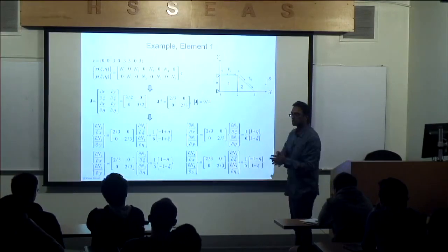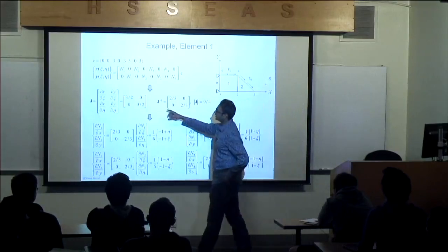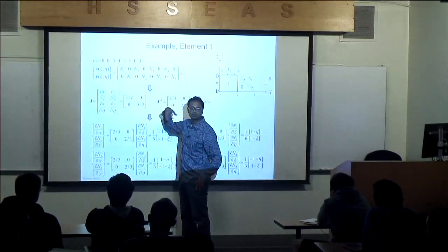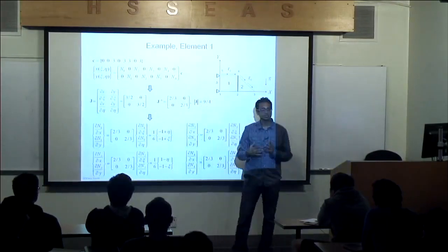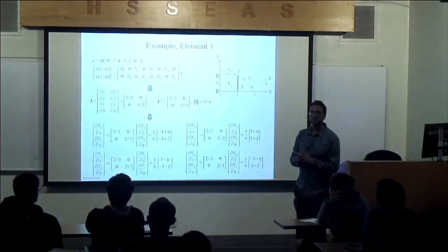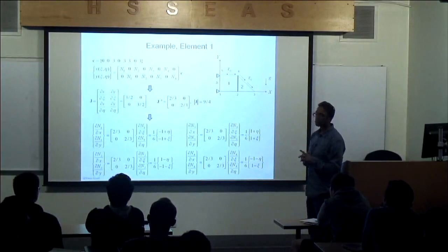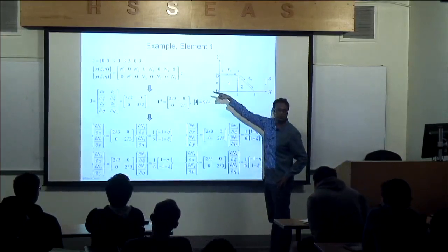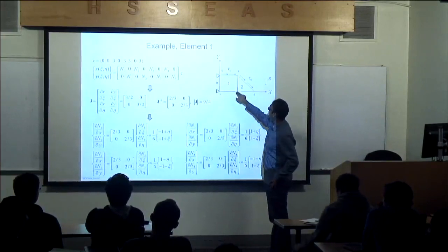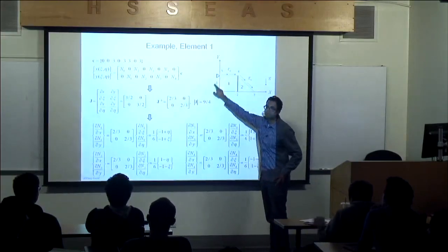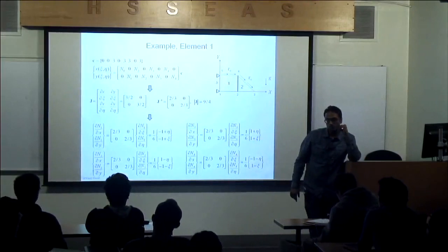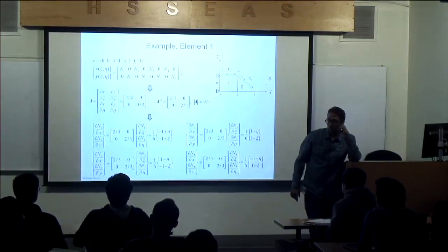In a lot of your situations, like your homework problems, all of these are populated with 1 minus C, 1 minus eta. You're going to have stuff here. I just chose elements for simplicity that will not have that situation, so I can explain to you the process, okay? You understand? The coordinates of the nodes you can calculate. For node 1, the coordinates are 0, 0. That's the first pair there. Second pair is 3, 0. The third pair is 3, 3, and the fourth pair is 0, 3. You can see those there. Any questions?